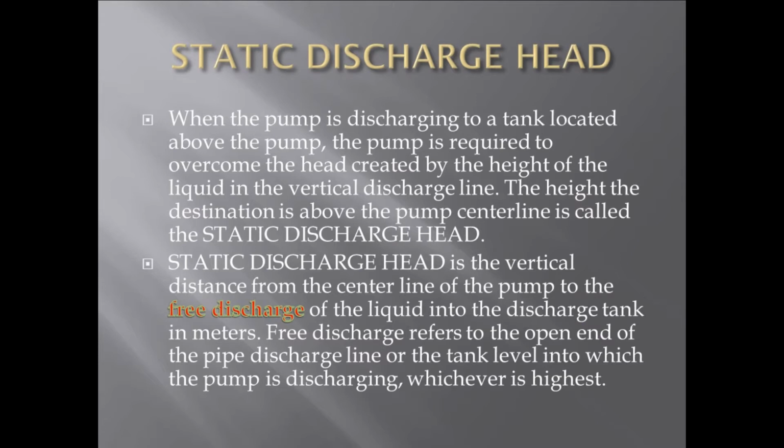Static discharge head is the vertical distance from the center line of the pump to the free discharge of the liquid into the discharge tank in meters. Free discharge refers to the open end of the pipe discharge line or the tank level into which the pump is discharging, whichever is highest.